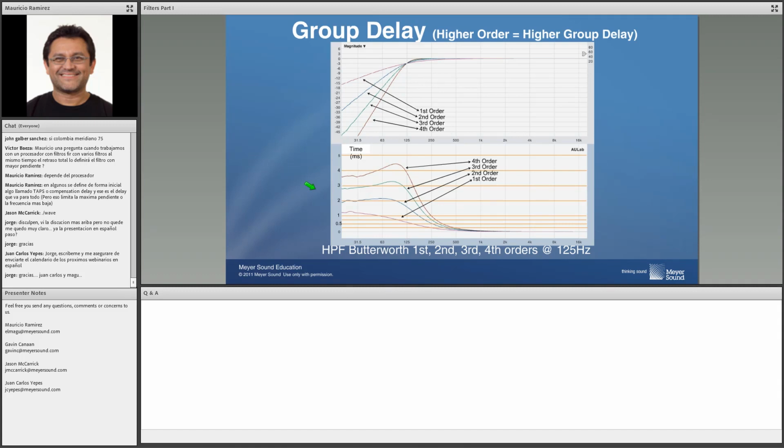But also, shifting up the frequency, in other words, higher cutoff frequency means less group delay, but in a bigger range of frequencies. And lower the cutoff frequency means more group delay in more narrow bandwidth of frequencies. That is the way it works.